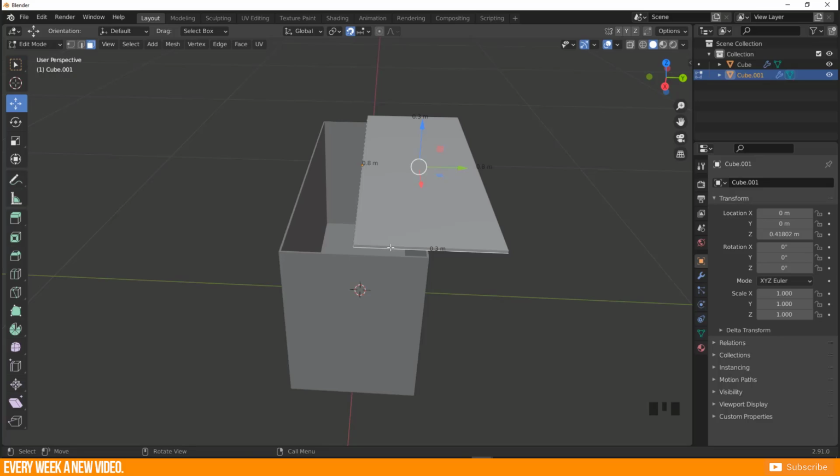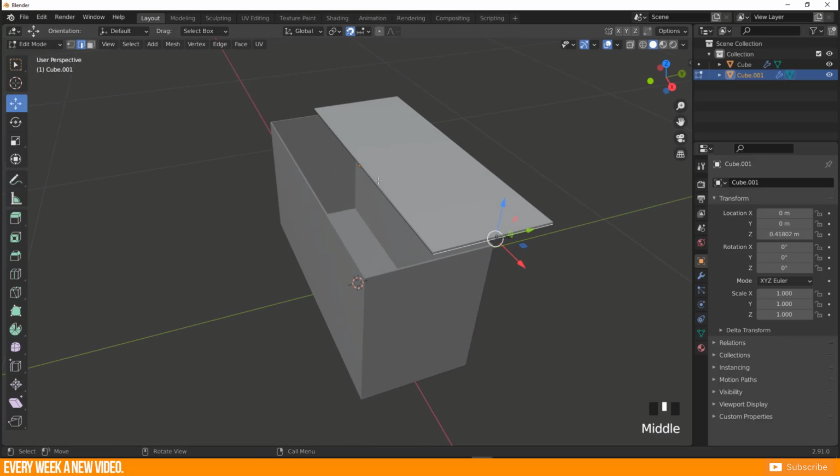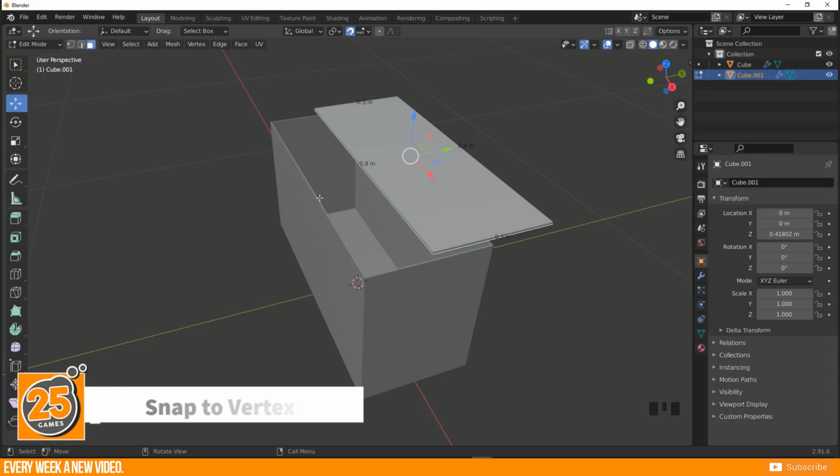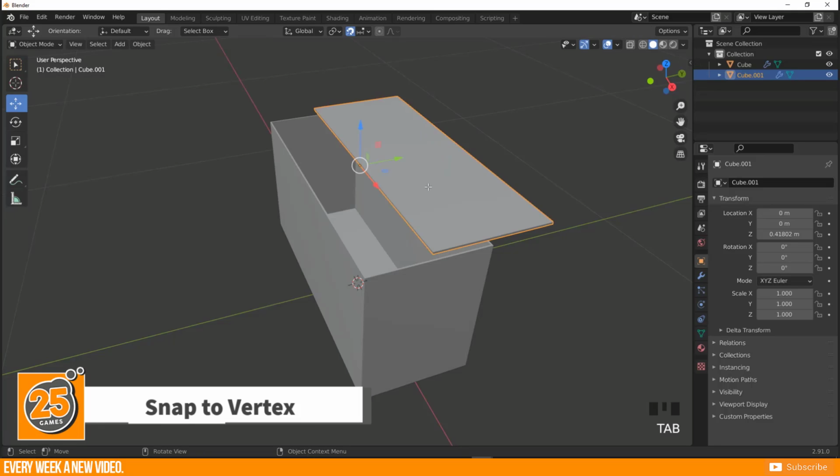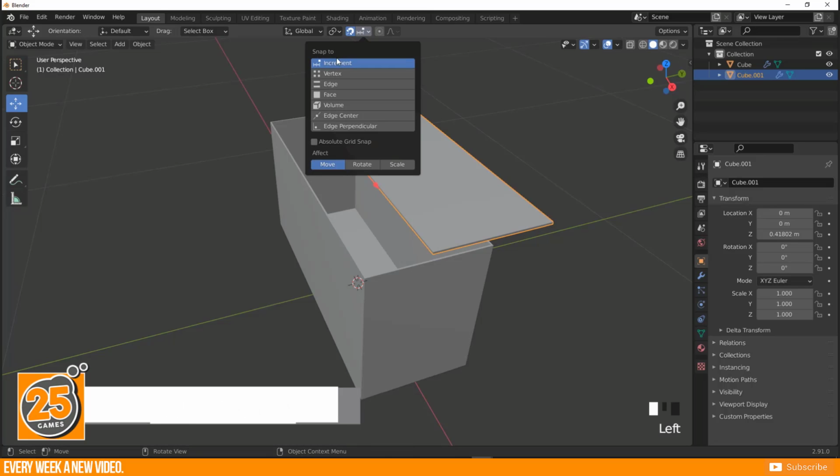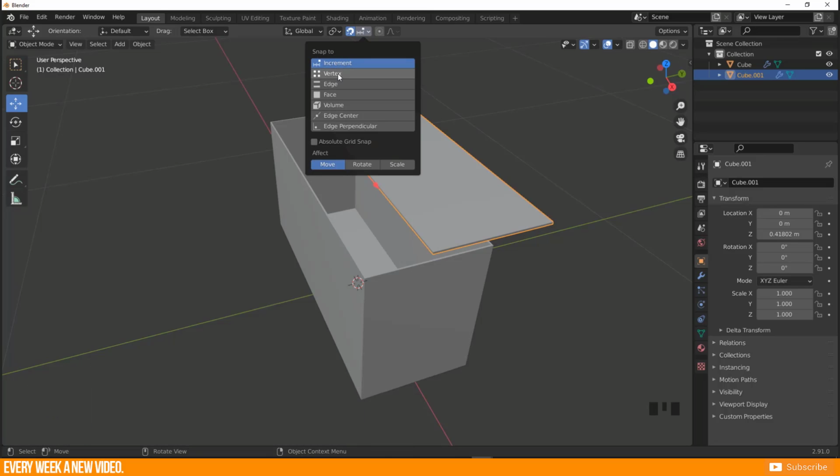And for example, when I press the edge selection mode now and select this one, then the gizmo will jump to this position. Or if I select the edge here, then it will be here as well, but when we select the face, it will be here. I want to bring this face now to the inner part of this. And for this, I go to object mode, and I will keep snapping, but change the snap to Selection. And I want to snap to the vertex here.